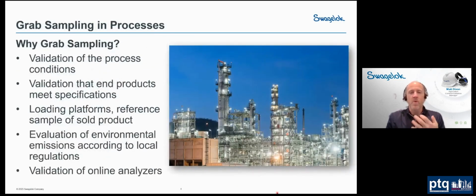So why are we doing grab sampling? What is the purpose? It's really all about validating the process and making sure that whatever is flowing through that pipeline meets specifications, whether it's your internal specifications or your customer specifications.